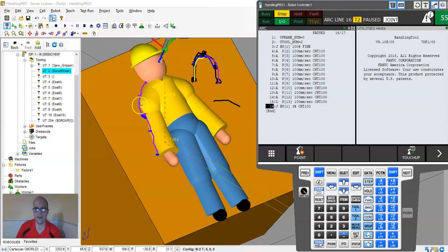But where things get complicated is when you're going around sharper corners. I know Motoman is really tricky like this, and this is how I was taught this, so I might be importing this into Fanuc, but I do think this is a helpful way of looking at arc commands: the more points you have, the better, because that'll line up more with the contour that you need.